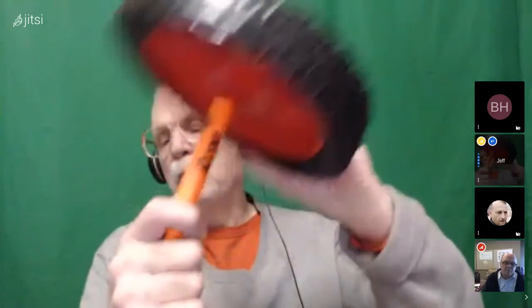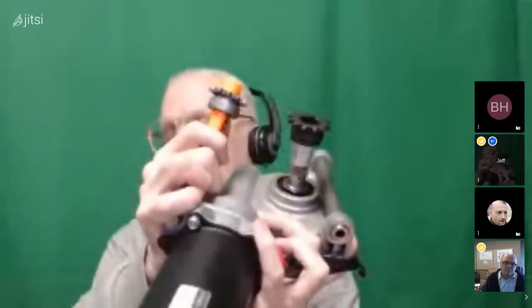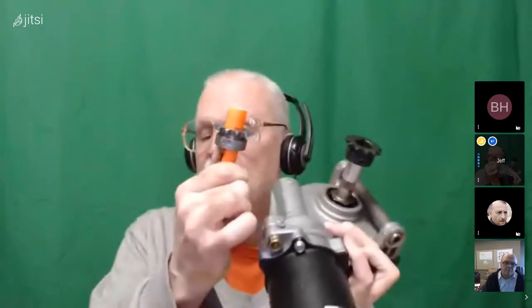So if I pull the steering wheel off, I could put a sprocket onto that where the steering wheel was, and then mount my motor down below like this, and just sort of chain between the two. I can't get the right angles here. So basically just mount this motor on the front of my plastic housing and then just run a chain. So that's going to turn the existing shaft. And I think I've moved it enough now where I could leave the sprocket right there and then put the steering wheel back on. I think I can get it to fit just like that.